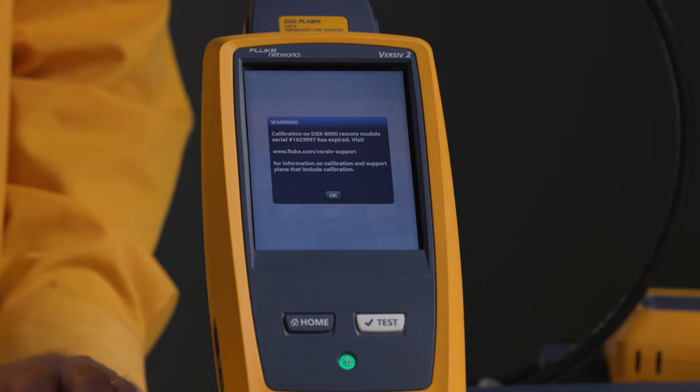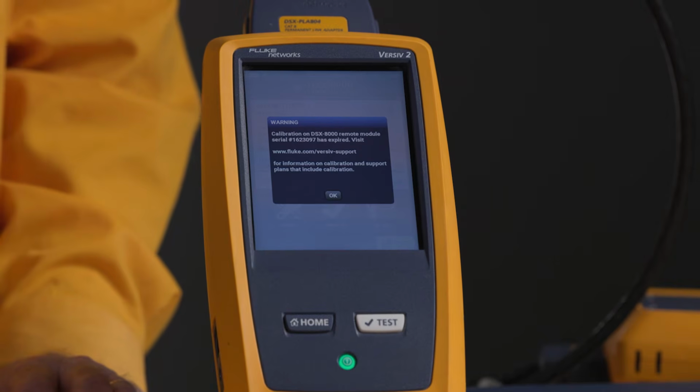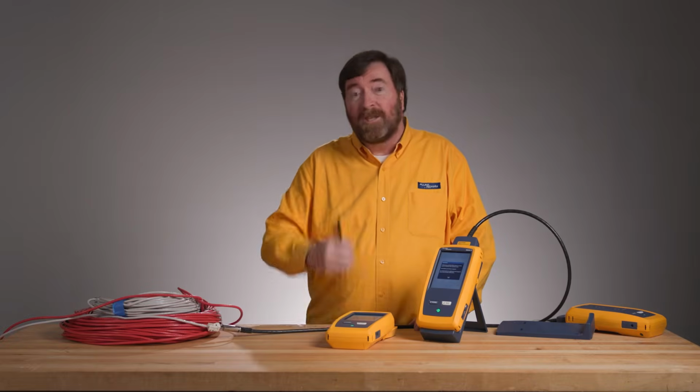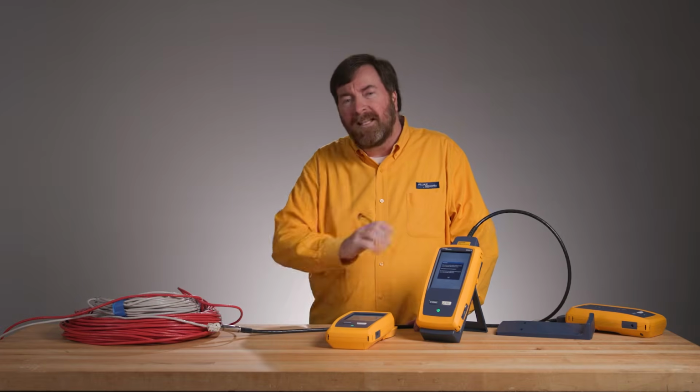From my perspective, if a measurement is being made, I want the measurement to be made accurately. If I'm at the grocery store and they're weighing my fruits and vegetables, I want an accurate measurement for that. If I'm installing my cabling, I want the most accurate measurement possible. That's why we'd like to keep our tester within its calibration period. If the cable's broken and I want to know the distance to where the cable's broken, calibration's probably less important for me.